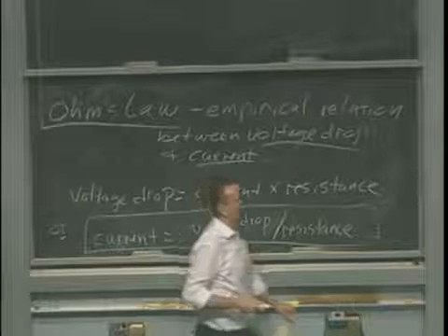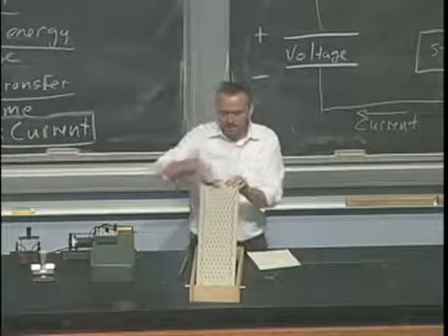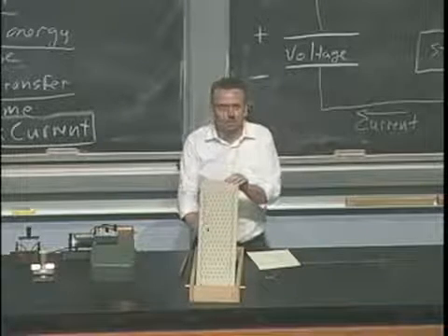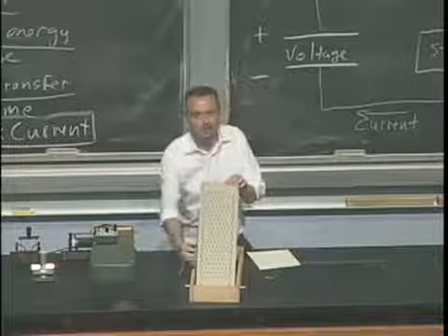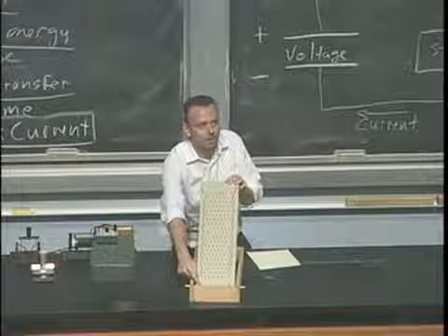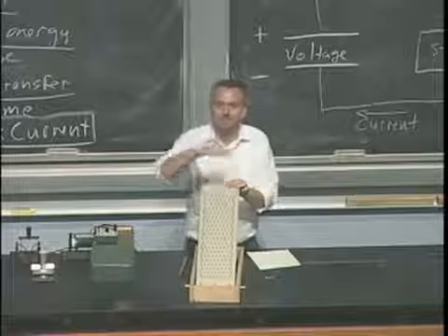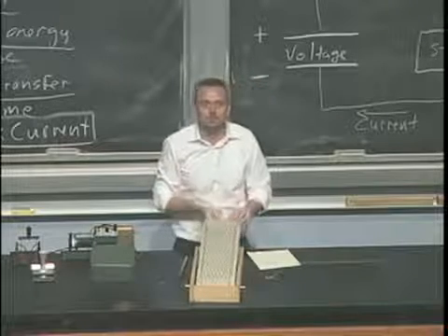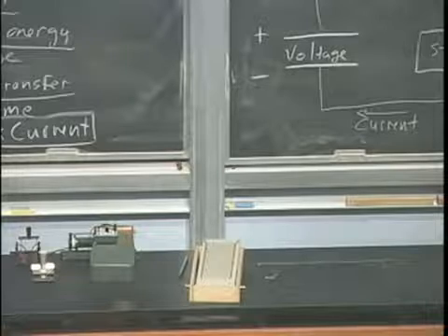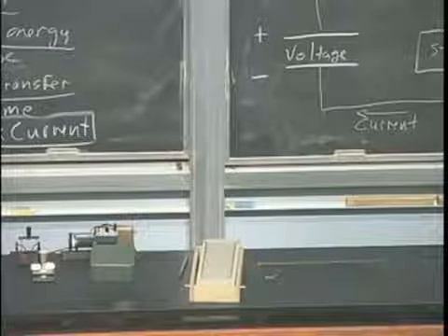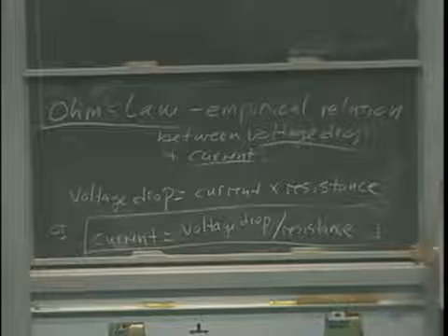As we already said over here, when there is a voltage drop, imagine that we've got this charge that's flowing through this resistor. When it's flowing through there, its energy is getting dissipated. So the amount of voltage drop across here is telling us how much energy is being dissipated by that marble as it's falling, or by the charge as it passes through there. That amount of resistance limits how much the current flows, which tells us how much power is being delivered to that part of the circuit. That power is being dissipated by the resistance in that circuit.